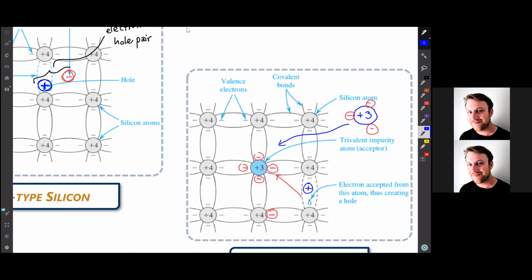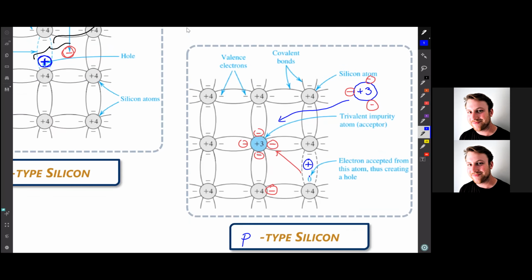I should say, we don't have that hole to balance out all the 4 electrons around the fixed acceptor. And so if that hole leaves, we will be left with fixed negative charge. And so that is why p-type silicon, when we deplete it of carriers, is full of fixed negative charges.